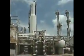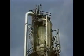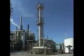One of the key elements of many process plants is a distillation system. It's important for operators to understand how distillation systems work because it's part of their job to make sure the systems run properly. The purpose of any distillation system is to separate a liquid mixture into two or more components. The separation takes place in a distillation column or tower.